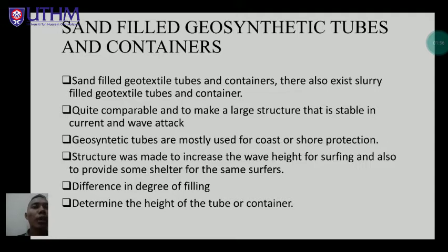Comparable, and to make a large structure that is stable in current and wave attack. Geosynthetic tubes are mostly used for coast and shore protection. Structures were made to increase the wave height for surfing and also to provide some shelter for the surfer. They also differ in degree of filling, which can determine the shape and the height of the tube or container.